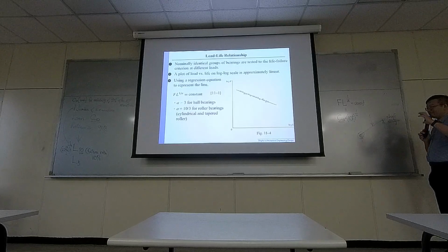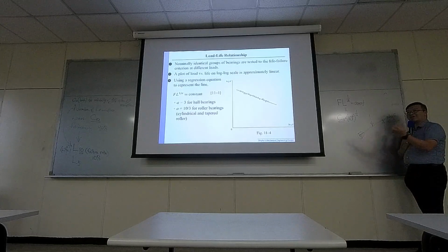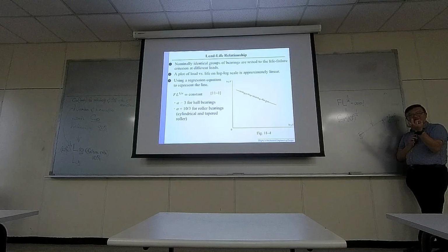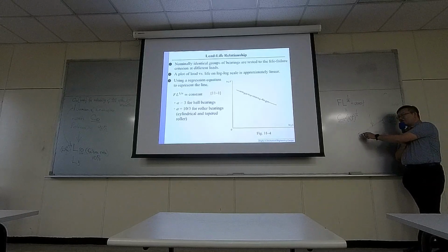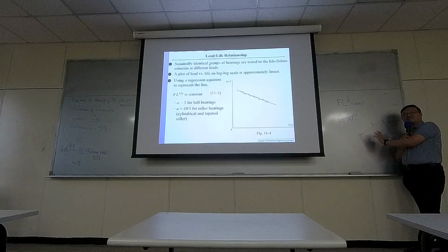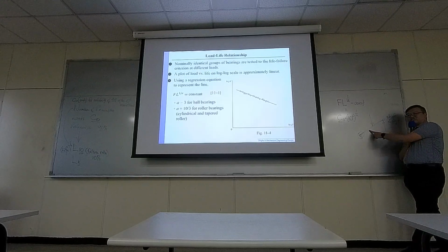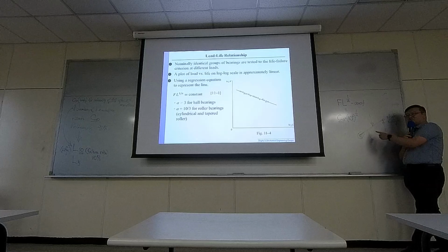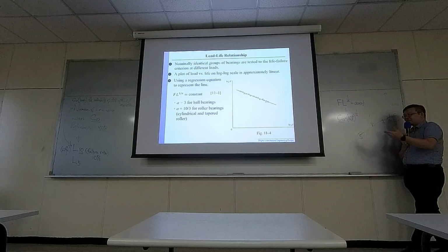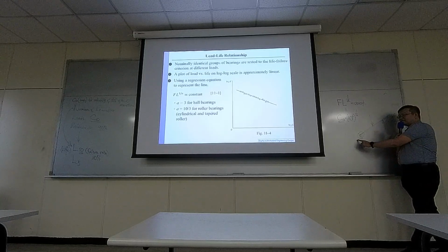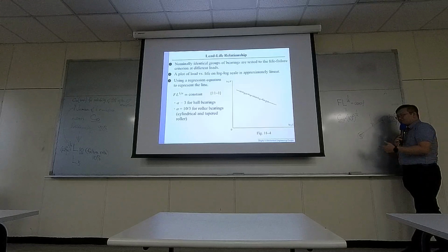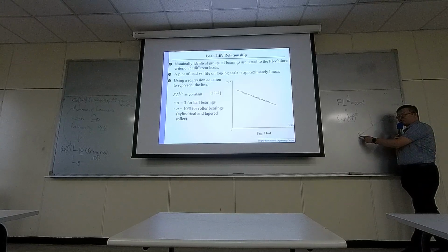And once you make a selection of your bearing, because of the bore dimension, you may need to change the dimension of the shaft. So everything is related, because maybe initially you don't have a decision on the shaft diameter. You just have an initial design, which suggests what kind of bearing you choose.